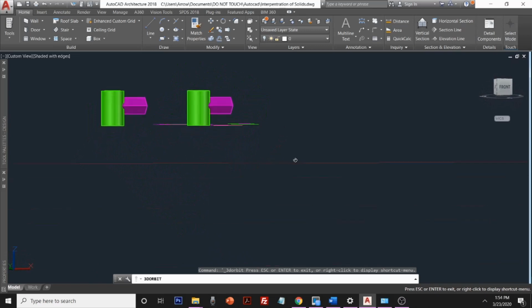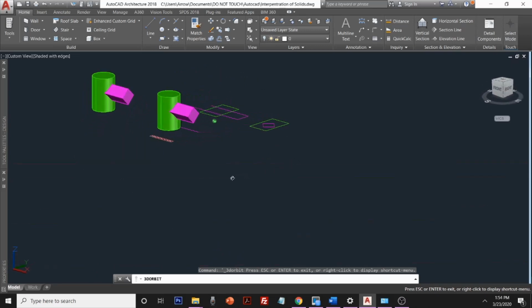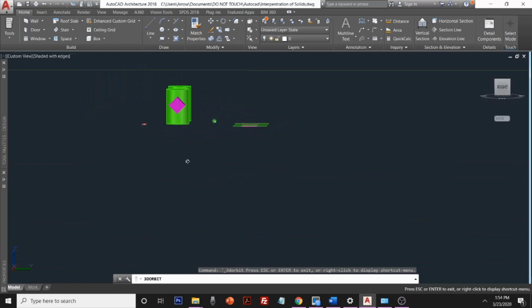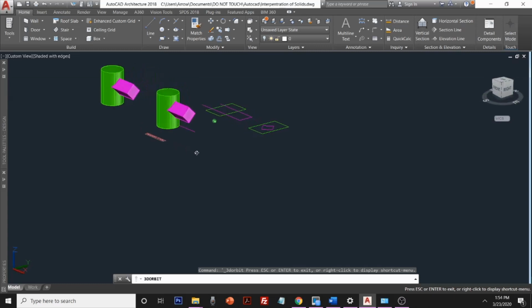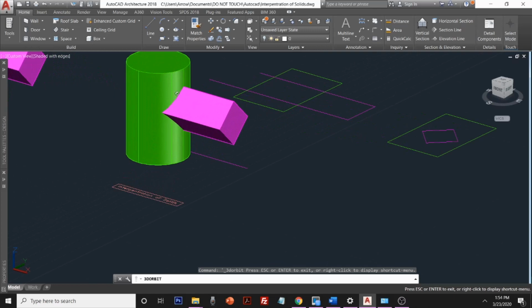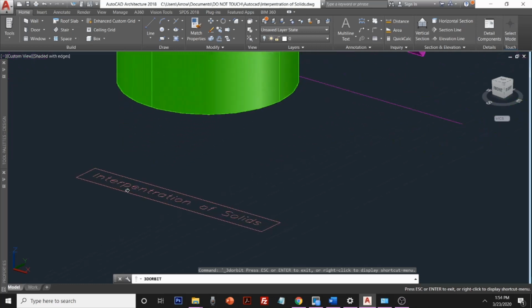And what would side view look like? Now let's go over to the right side of it, and what you end up with now is just the same rectangular shape representing the cylinder, and a diamond in the middle that represents the cuboid that's intersecting. Now the assignment or this activity is asking you, what would this curve look like? This is where most of your marks would come from. Being able to trace out the pattern of the intersection, as the topic it says, is interpenetration of solids.